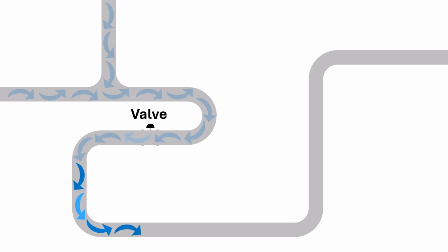Afterwards, the flow goes to a vertical straight pipe going downwards, which we also want to avoid because air pockets can form here. We finally get to a long horizontal straight section where laminar flow can form. This would be a great place to mount a flow meter. As the pipe turns, avoid mounting next to all bends.